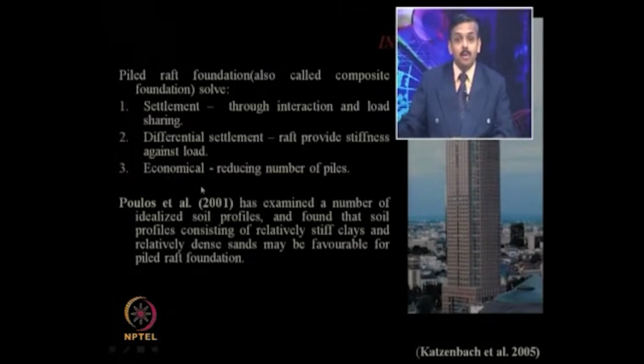Why is it very economical? Because in this case you are considering the effect of the raft also, which is neglected in the case of only a pile foundation. We always put the pile cap, but we never take the effect of the pile cap into account. So, using this combined pile raft design approach, you can get a reduced number of piles required for a particular loading. That is why it is very economical.